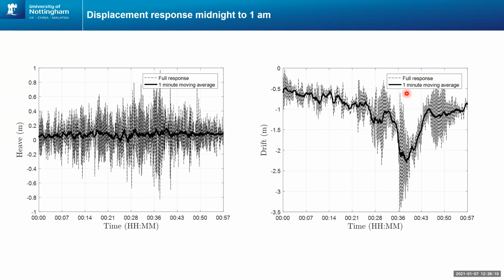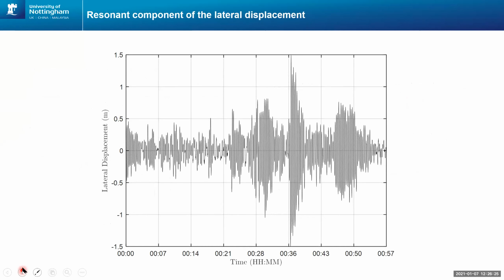And superimposed on top of that is a sudden dynamic response, plus or minus 1.5 meters, which looks something akin to a step response of the structure. If we highlight just the dynamic behavior for a moment, you can see that extreme pulse occurring here at about 36 minutes past midnight. Now, what was happening at that time on the bridge?